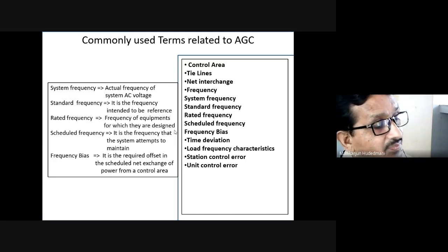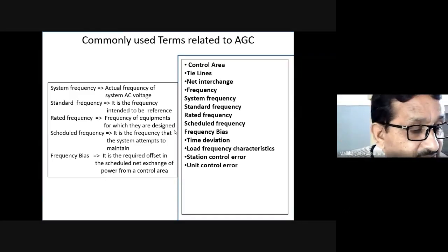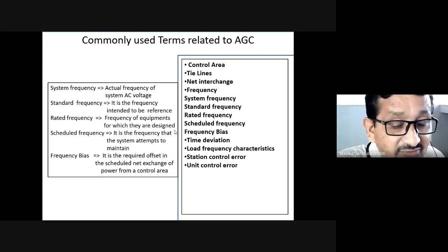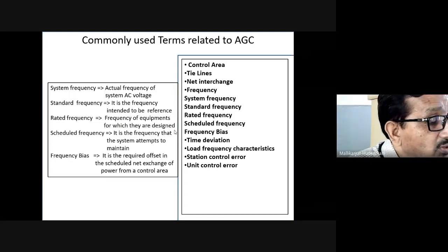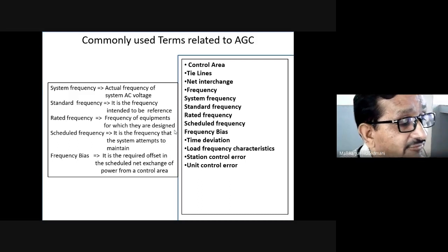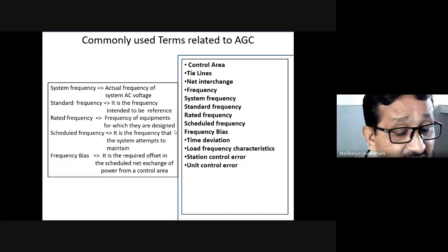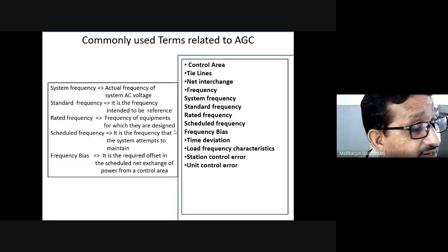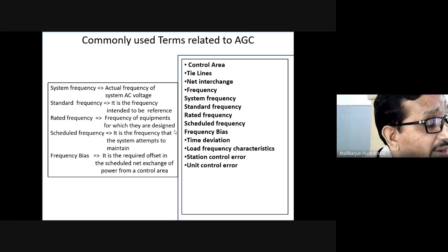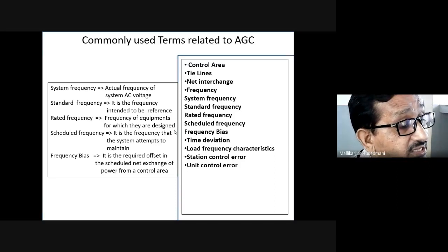For example, you have purchased some measuring devices from the USA for your Indian setup. Before getting the 50 Hz set point on it, you have wrongly not changed the frequency to 50, and it is running at 60. Then the 60 Hz based design inside the operational controller will definitely respond accordingly. The frequency in the continent where you are installing is 50 Hz, but the internal setting in that component is 60. Once installed, the system might project wrong things, protrude errors into the system, and erroneously function.